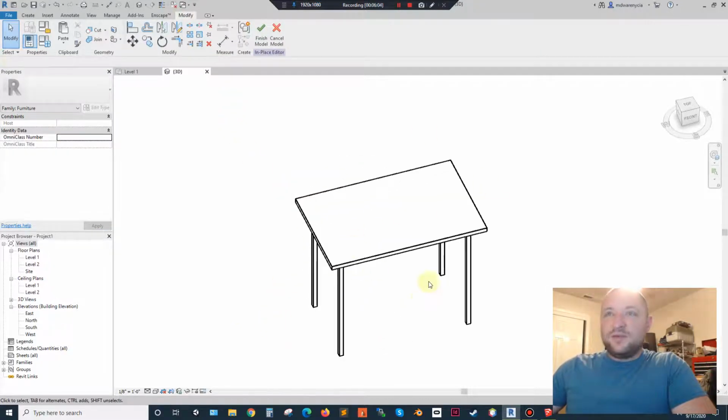So anytime I'm working in this top-down axis, I need to remember that I need to think of where the ground axis is and then move up from there. Okay, so now that I have this, let's say that what I want to do now is go in and add a couple extra little legs or cross members or things going on in here, but it's something that I won't be able to just do a straight extrusion, because an extrusion is basically the profile pulled out.